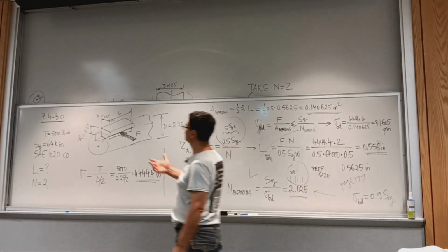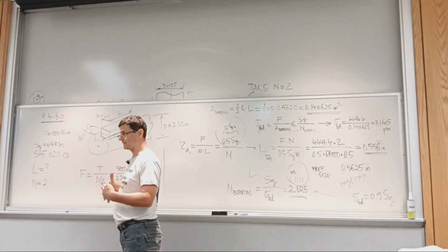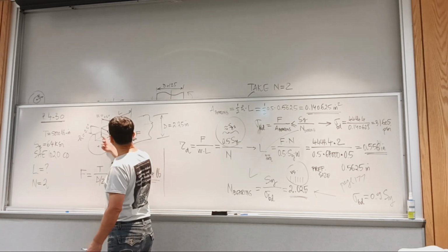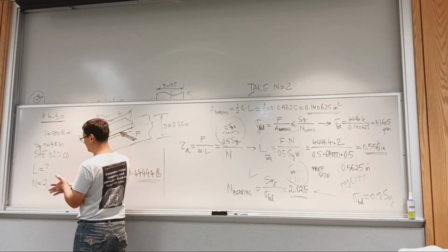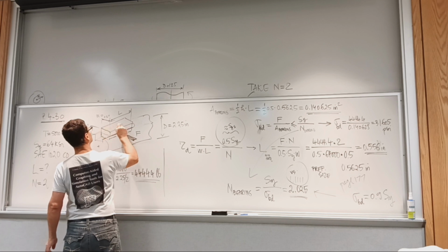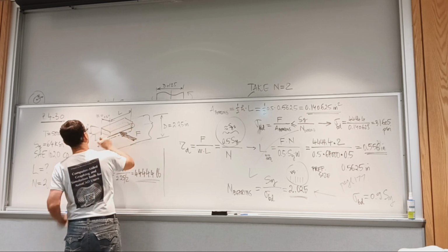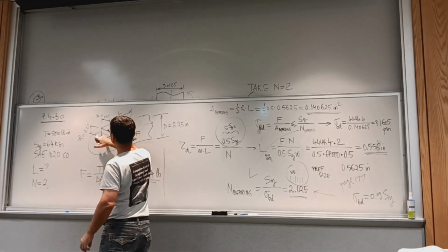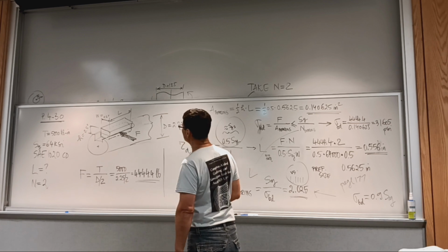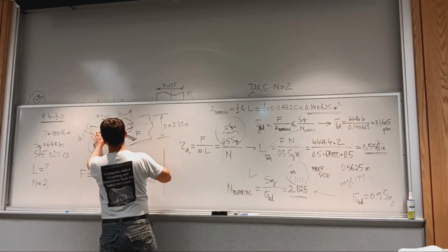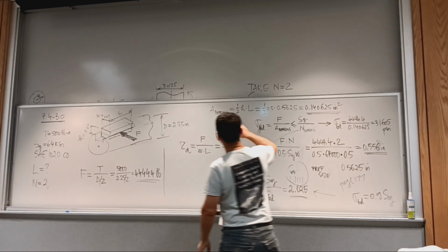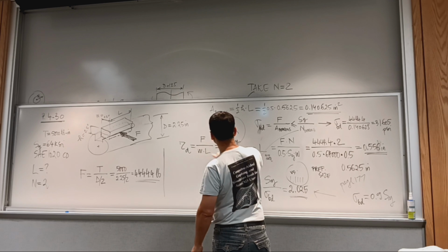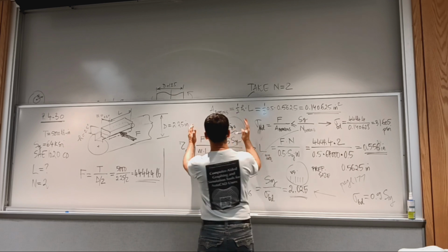Once you have the shear force, you can calculate the shear stress. I started with the shear stress because it's chapter 4 and talks about shear. Bearing stress was chapter 3. And we calculate the shear area. In the shear area, you have the square key, and there would be a relative sliding between the two pieces of the key as you exceed its capacity. So the shear area is going to be a length, which we don't know, times this width. So we calculated the design stress and shear stress, given force, shear area with L unknown.